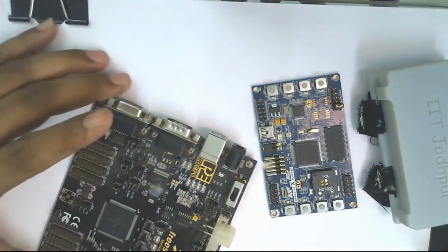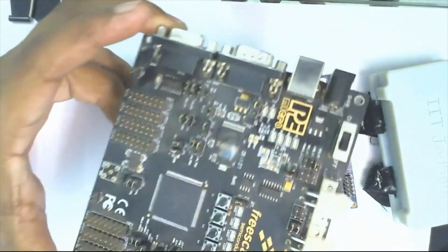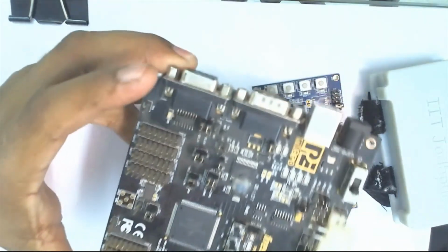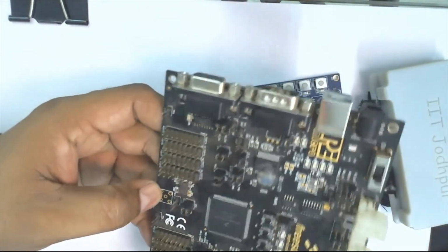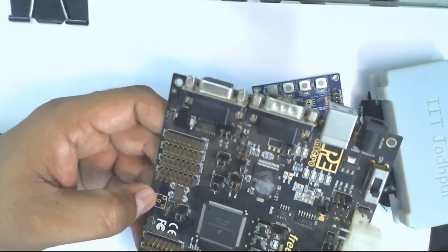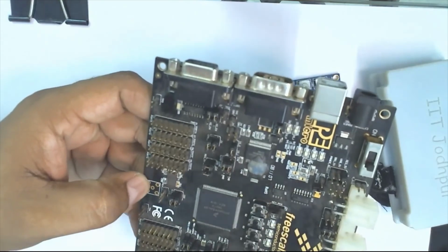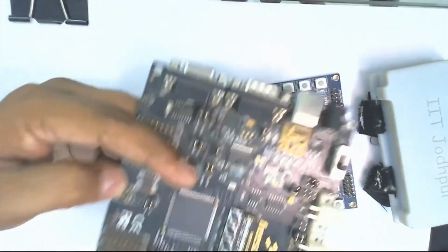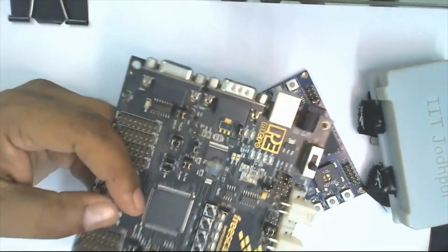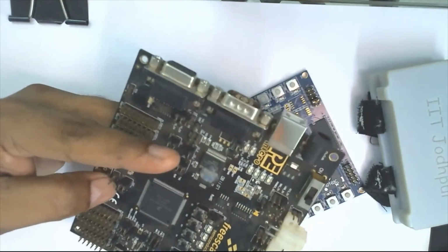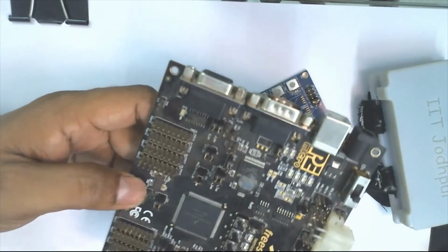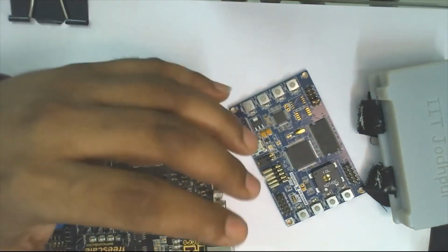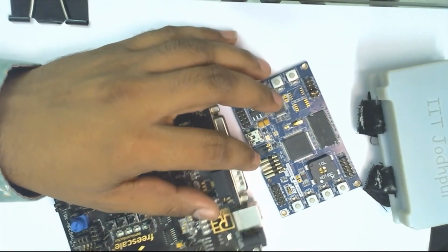Okay, whereas this is the medium scale embedded system, in which we may need to use application specific standard products, for example such controllers, some modules and fuse bits, some memory chips. Along with that, we may need to use TCP/IP protocols. We may need to use an RTOS even, and we may need to use a simulator, debugger, and integrated development environments for this. So basically, the complexity increases as we grow from small scale to sophisticated embedded systems.